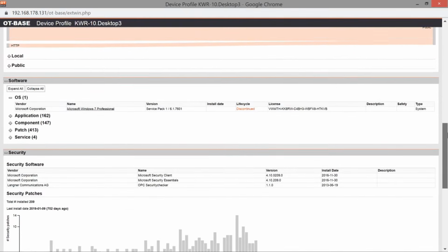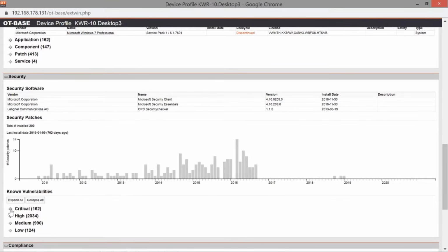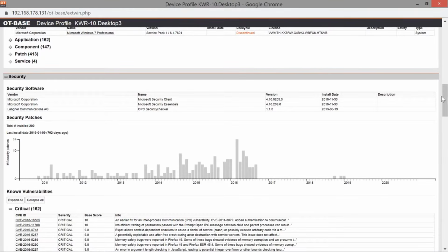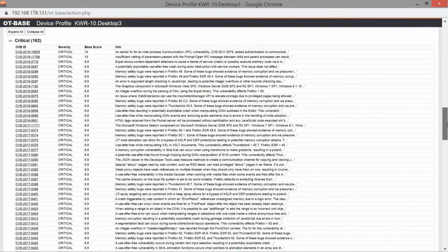For the vast majority of Windows installations in OT, there is no automatic patching, and for a good reason. Setting aside that computers in OT often run 24/7 and cannot be rebooted when IT wants to, a security patch is a configuration change, and your OT application isn't necessarily happy with that change. The vendor in question might not be happy with that change either and told you right away that your warranty will be void if you install unapproved patches.